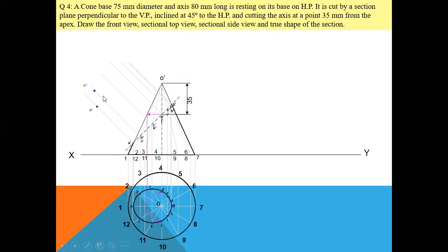On that same line, you will get this L also, because you are getting L in top view again on that same line. This time you will measure L to this horizontal reference line, this much length. Again, you will place your compass at this point, and on this projection line passing through B dash L dash, cut an arc.